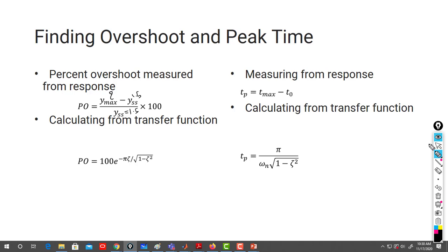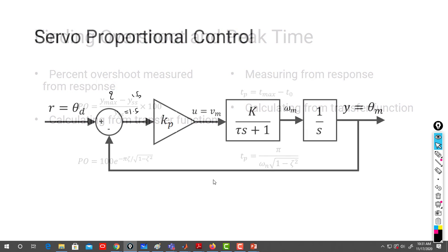Alright, so we also saw the percent overshoot, times 100 if you wish; if you don't, without the 100 it's not in percent. We know this formula, but I also recommend you use the curve I gave you, so it's much faster in your exam and saves time. Instead of doing the calculation, you use the curve. Okay, pi over omega d, this is omega d.